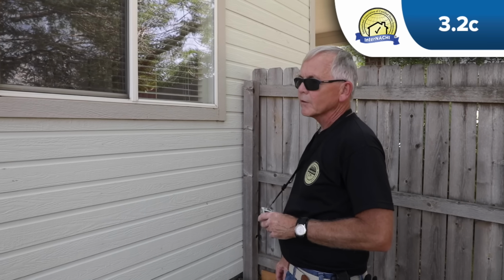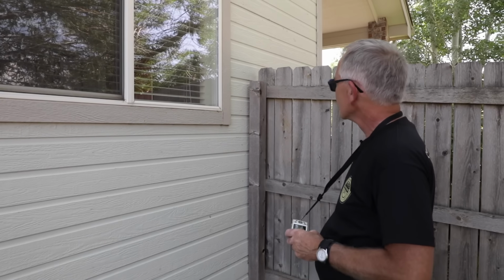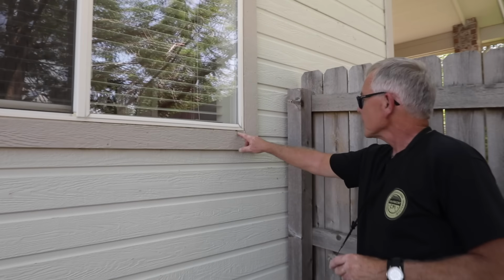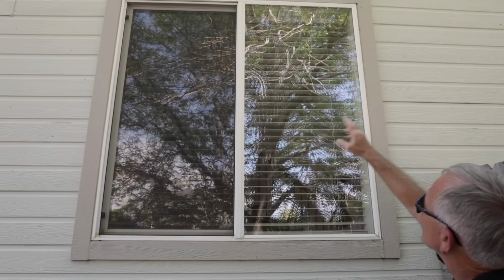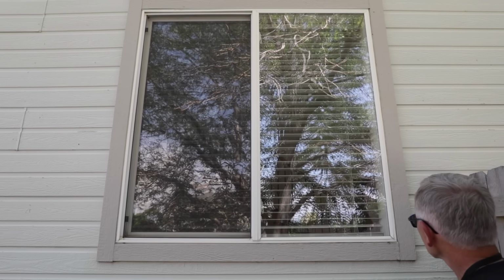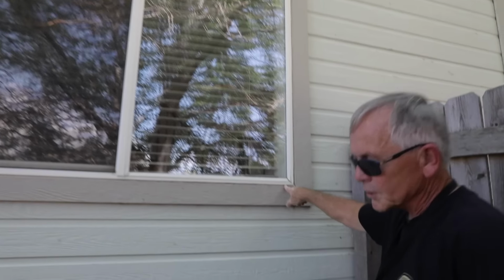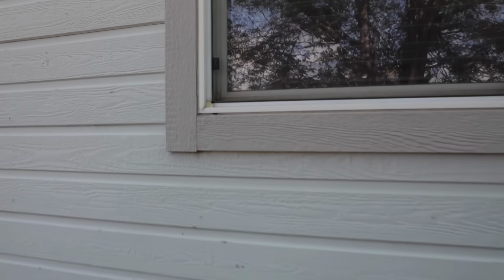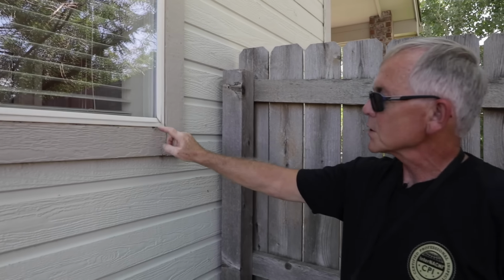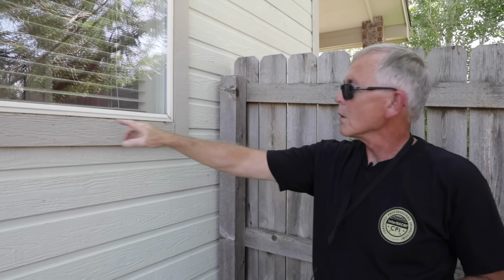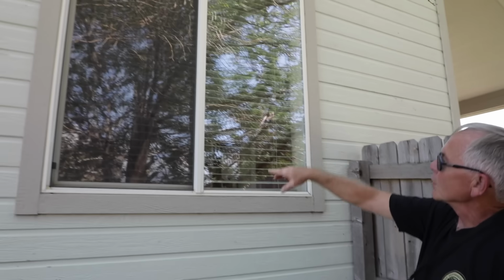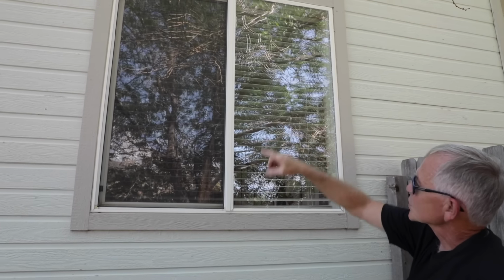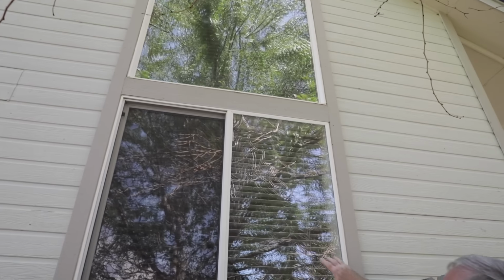So now we're going to do a representative amount of exterior windows. The things that I look for is make sure that the window frame isn't cracked, broken. We don't have any distortion of any kind. We want to make sure these weep drain holes on the bottom frame are open and not plugged up. This is where any outside rain or any kind of moisture that comes in, this is what allows it to drain out of the track of the window. So I make sure those aren't plugged up. I will check the screens, even though that's not part of the SOP, but I want to make sure that the screens aren't bent. These two windows here, they look good.